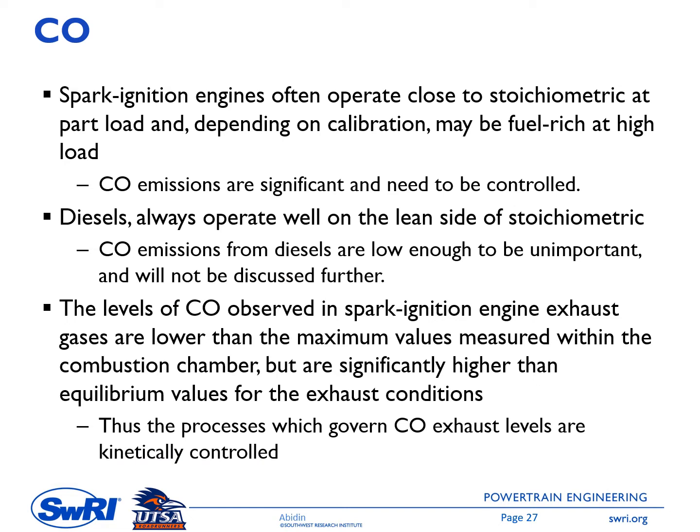For spark ignition engines that operate close to stoichiometric at part load, and then depending on the calibration, maybe fuel rich at high load, the CO emissions are significant and need to be controlled. Diesel engines always operate well on the lean side of the stoichiometric mixture, so the CO emission is low. Therefore it is unimportant in diesel engines.